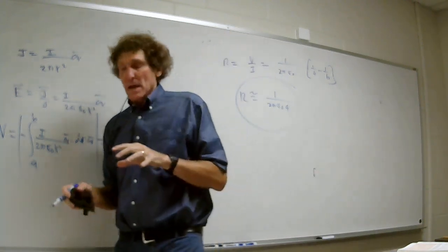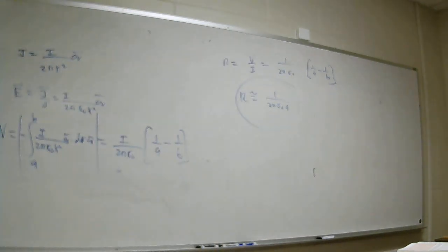Now, in the real world, and I'm not an expert on this, if you wanted to get an approximation of the ground conductivity, assuming it's uniform, which is an assumption but in a lot of cases is true, what they'll do is, out a long ways away, say 20 meters away, drive a grounding rod. They'll put a rod deep.